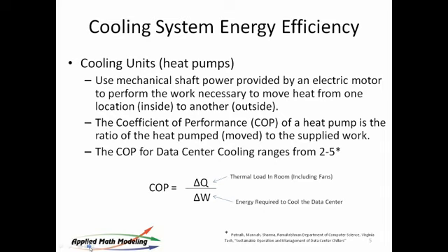Now, the heat pump manufacturer or the CRAC manufacturer will also talk to you about COP. Theirs tend to be higher because they're not talking about the COP of the room. They're talking about it of their machine in an ideal environment. Furthermore, they use something called EER, which is actually a kilowatts per ton ratio. Liz and I tend to use COP because it's dimensionless, it's kilowatts per kilowatt, and it's simply a ratio of the amount of heat rejected compared to the amount of work required, using the same units, to get that heat out of the room.